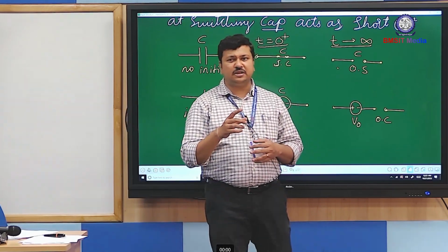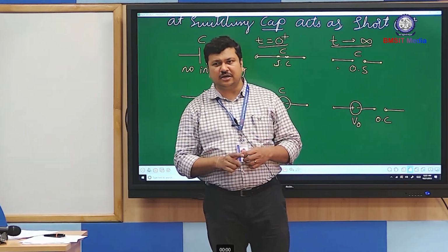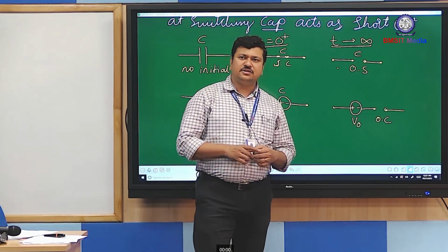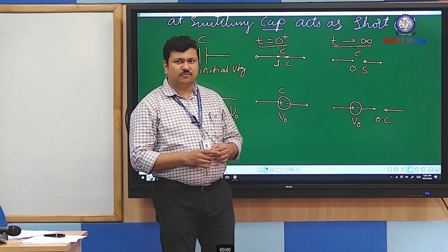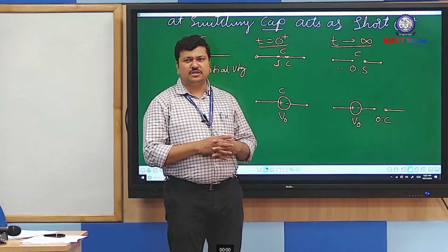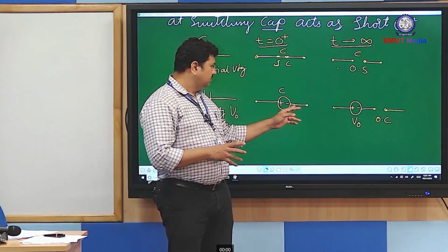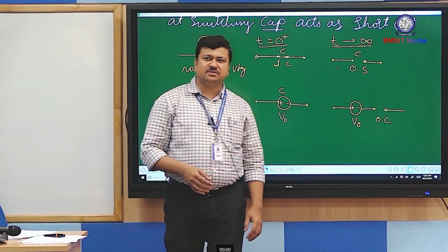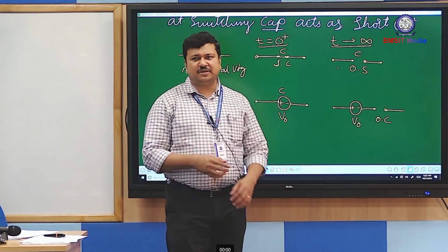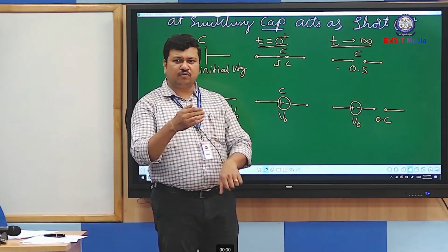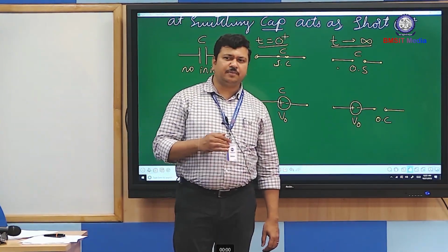So there is an instantaneous change in voltage across the inductor, but the current in the inductor is not changing instantaneously. Therefore, I can say current lags behind voltage by some angle. The complement is true for the capacitor. The voltage in a capacitor doesn't change instantaneously, therefore voltage lags behind current in a capacitor.